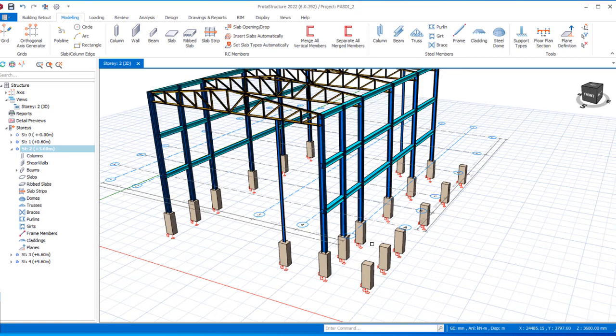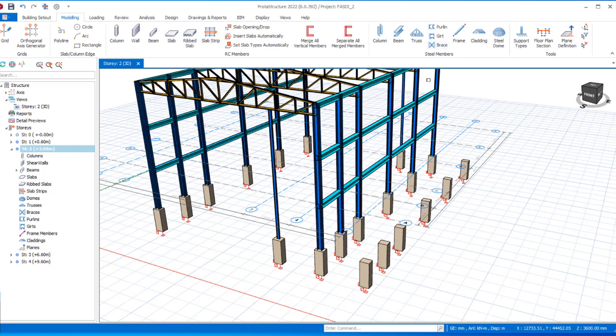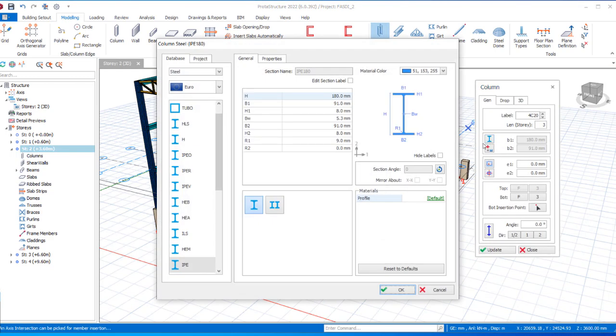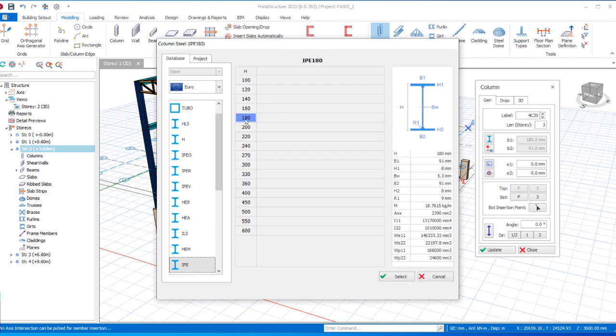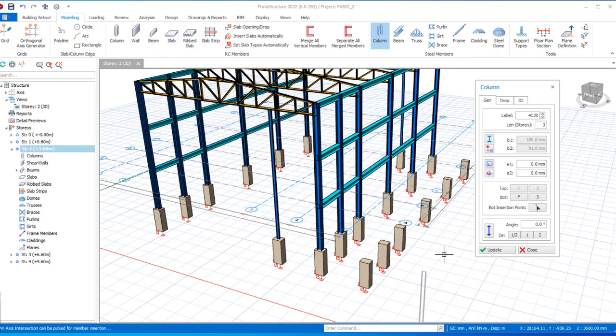All right, so at this story now, you just have to navigate to the steel stanchion or steel columns right there. Choose our sections. Okay, IPE 180, the same sections. Click on the OK options. We are going to rotate it this way. Click on the OK options.